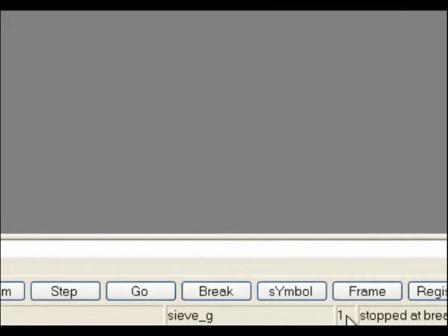If the system runs onto a breakpoint, the complete system halts, not only one CPU, but all CPUs that are handled by the SMP system. So running on the breakpoint, regardless which CPU runs onto the breakpoint, causes both CPUs in this case to halt. So the system is really halted. The debugger then automatically changes the focus to the CPU that caused the breakpoint. And in this case it was CPU number 1, so we are working on CPU number 1 in this case.